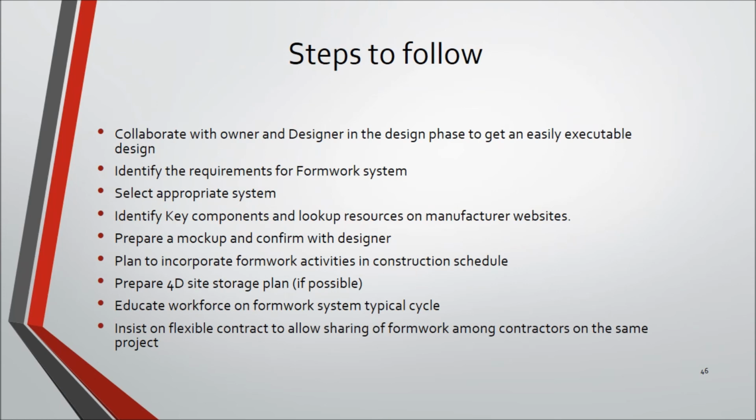The step-by-step guidance or the gist of the presentation shall be in the following steps. First, collaborate with owner and designer in the design phase, to get an easily executable design. Remember, it is best to do changes at the beginning. Second, identify the requirements for formwork system given the project design and construction methods. Third, select appropriate system which is available easily, and is easy to use.